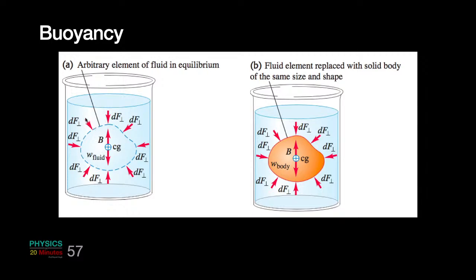Now this pressure is going to be less on the upper section and more on the lower section, because we have just discussed that as you go down in the fluid the pressure increases. So the upward pressure will be more and the downward pressure will be less. As a result, if I calculate the force on the inside section, then the force on the upper part, which is net downward, will be less, and the force on the lower section, which is net upward, is more. As a result, there is a total net force which acts in the upward direction. So the net force on this section due to the external fluid pressure works in the upward direction.